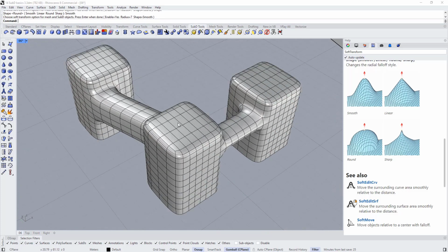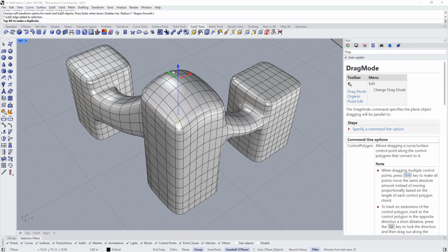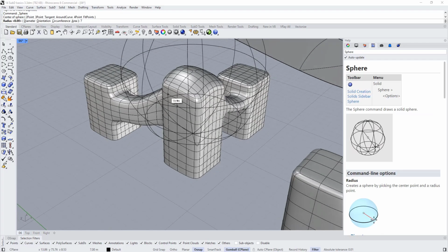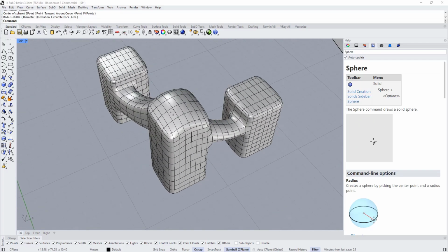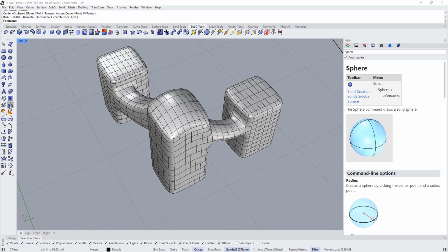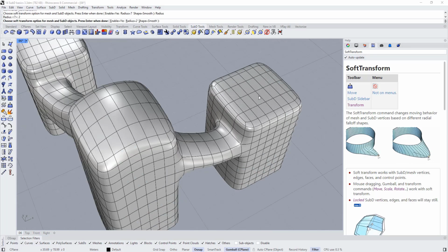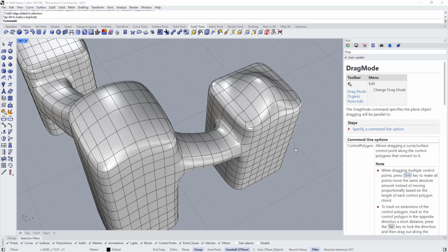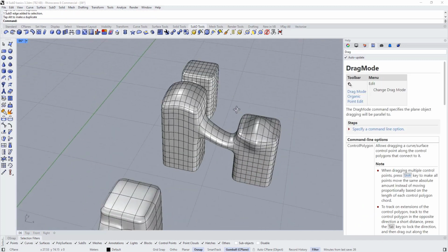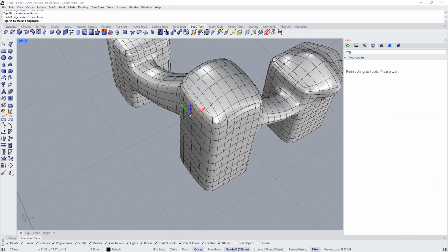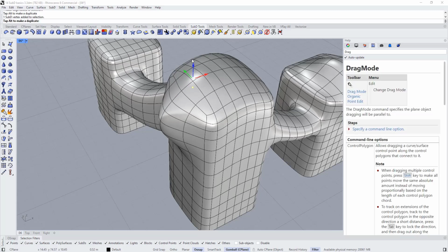Then right click. Now, if I select an edge or a face, as you can see, it is not just affecting the face; it's affecting everything around it with a radius of 7 meters. Just to understand the scale, let's draw a circle of radius 7 meters. So this is the range of its effect. Let's go to SubD again, and let's change the radius a little bit, make it 2 meters. Then if I right click, I can start adjusting, and now the radius is a little bit smaller. This is very useful when editing something like this with a lot of faces and edges.